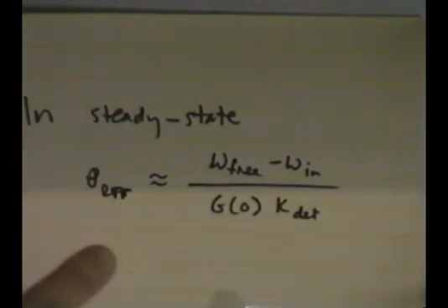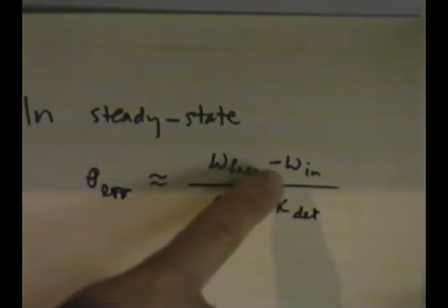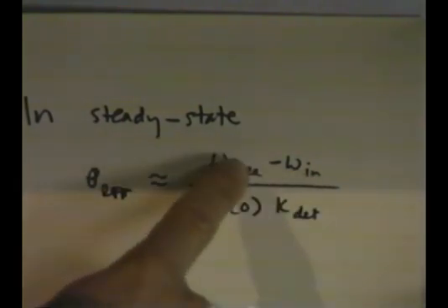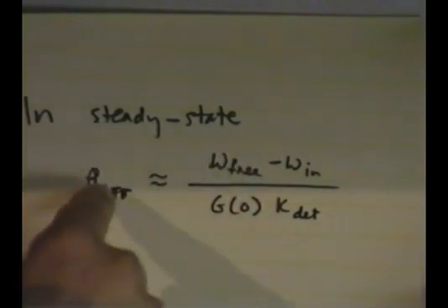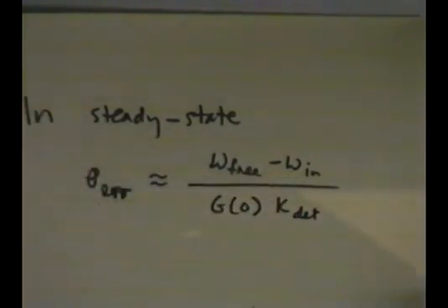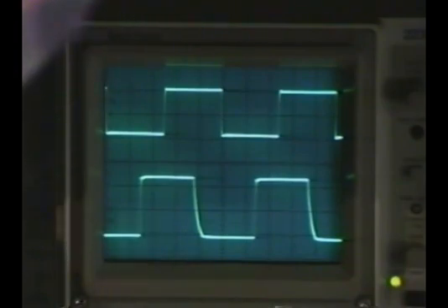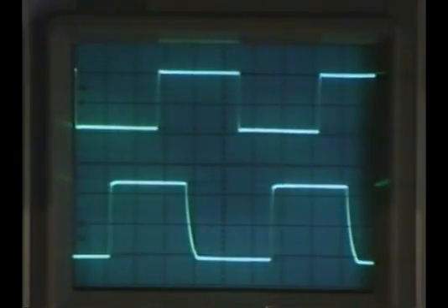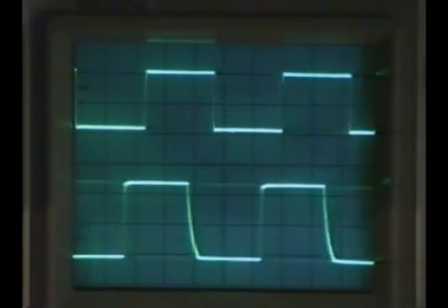That's all this calculation is, or you can work out all the transfer functions and things like that. And so this is very, very interesting. It says that the phase error will be 0 when omega n is omega free, which means 90 because everything's offset by 90. And then it will decrease as omega n increases, and that's precisely what happens. So everything is predicted by this very nicely. There you see the whole lock range very nicely. Loses it, locks, and then loses it.